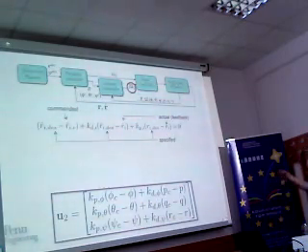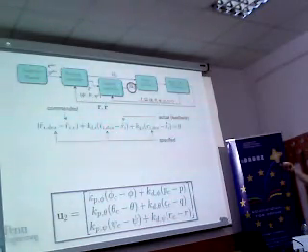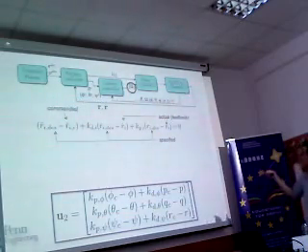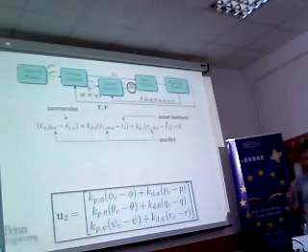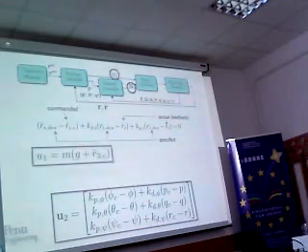So you can see here, this is the desired velocity, and this is the actual velocity. So we will take the error for this one, and now we need to calculate this one in order to get zero. So this algorithm will make sure that our current position will reach the desired position. The commanded acceleration will then tell us what thrust we want to apply with the rotors. The only thing that's left now is to determine the commanded roll, pitch and yaw.